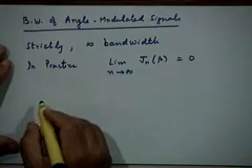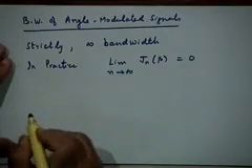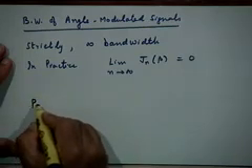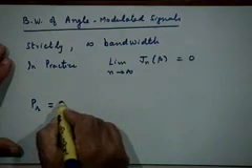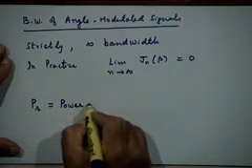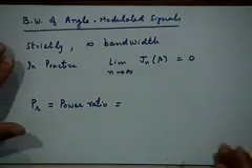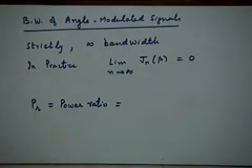So how do we define the bandwidth? To define the bandwidth, let me first define a ratio E_r, which I will call the power ratio, in this manner. Suppose I consider k sidebands on either side of f_c, and look at the energy contained in these 2k plus 1 components, from f_c minus k f_m to f_c plus k f_m.